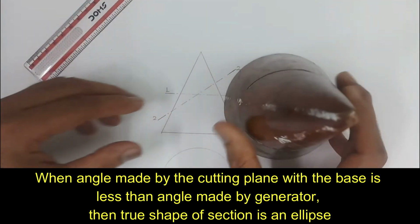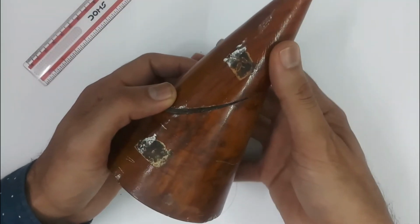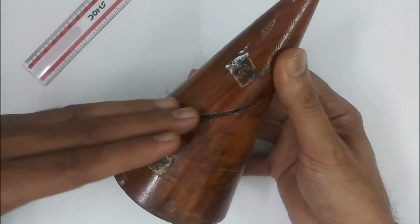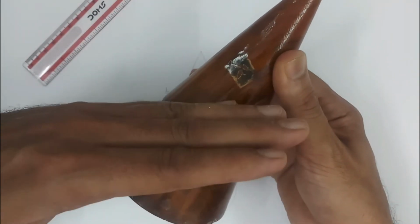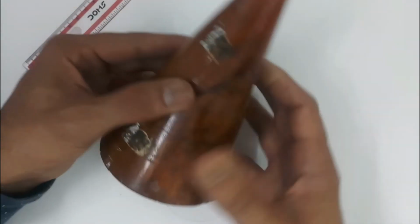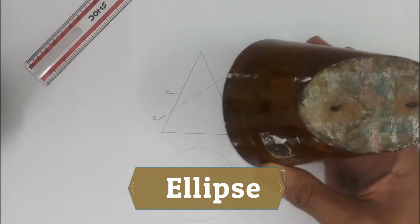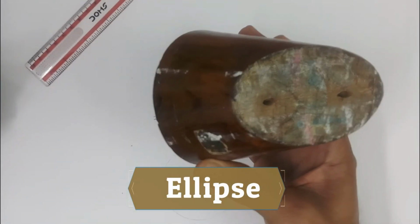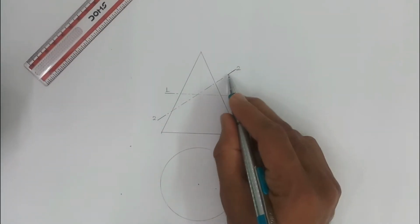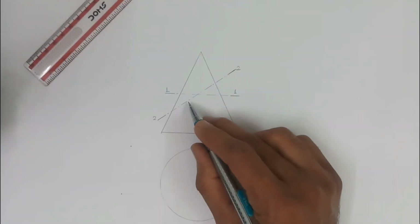With a demonstration we can see, this is the cone which is cut by a cutting plane. You can see the angle made by this cutting plane. This is the way it is cut. The angle made by this cutting plane with the base is less than the angle made by this generator with the base. So if I remove the top portion containing the apex, then the true shape of section in this case is an ellipse. So section plane 2 2 is going to give you the true shape of section as an ellipse.